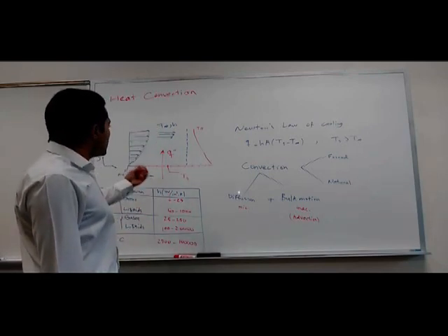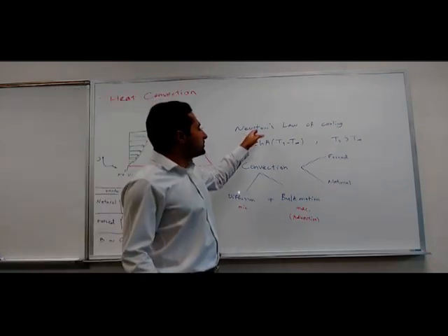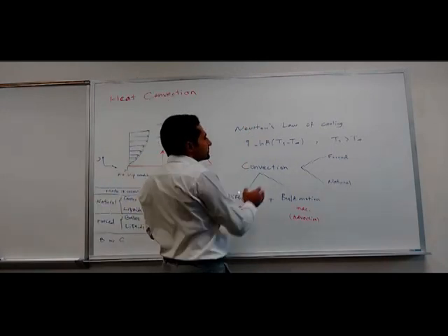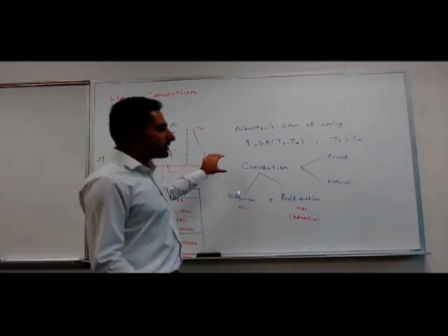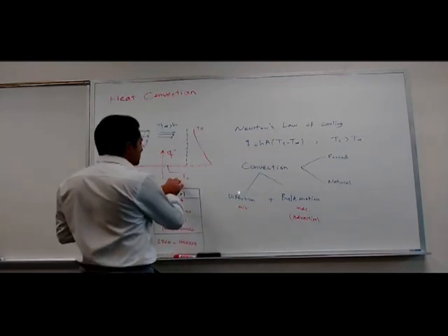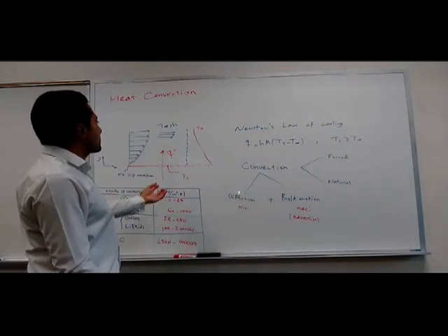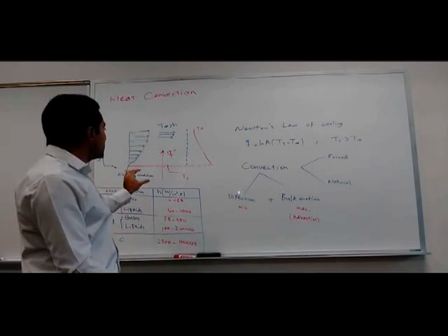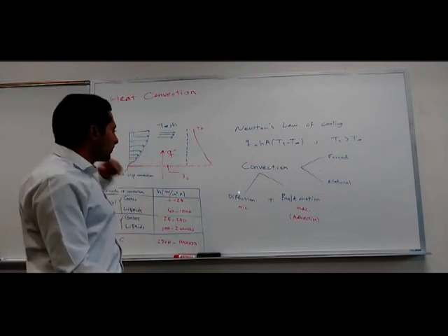If you want to calculate the heat transfer here, you need to use Newton's law of cooling, which says that the heat transfer is equal to heat transfer coefficient times the surface area times the temperature difference. If the temperature of the plate is greater than the temperature of the fluid, heat flux will occur from the plate to the fluid.